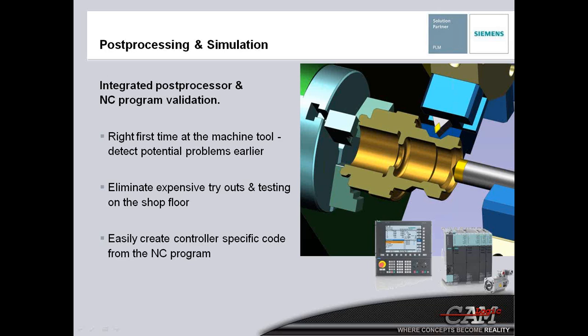By providing good output from the CAM system, we should be able to reduce this time and effort and still avoid machining mistakes. This is even more important as machines become more advanced, with the IntegrX line from Mazak or the Mori Seiki NT line. With multiple machining options going on, it's harder to be certain of what the machine will do just by inspection of the G-code.